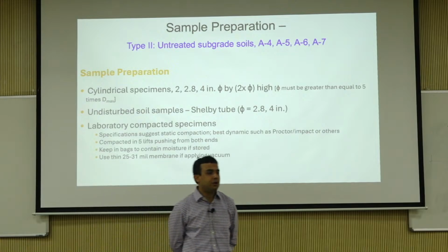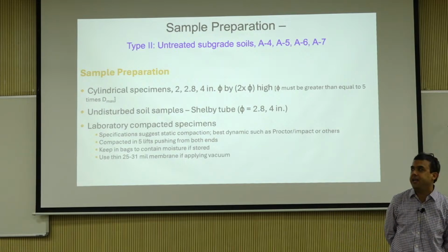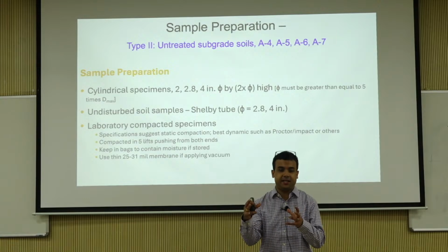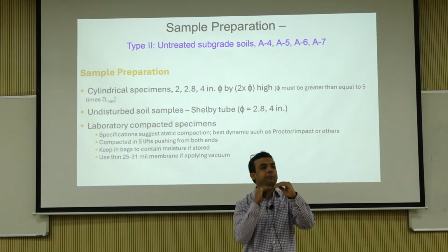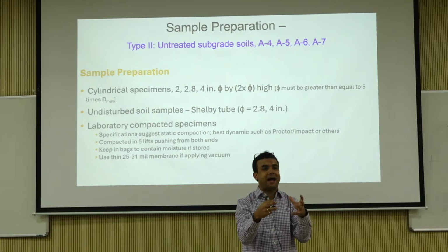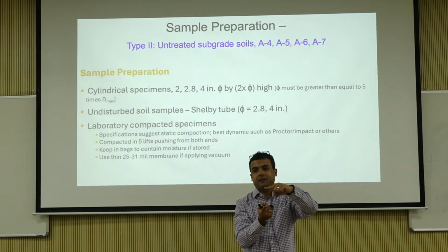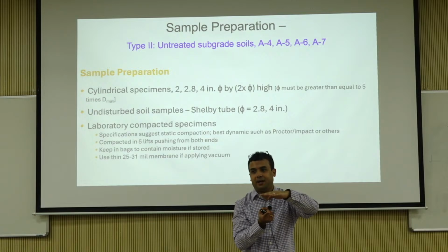Okay. So there are different ways. For example, the way I used to run it is I would calculate the target density. I know the volume of the material, and then I would say I'm going to compact in 5 layers. So I know the mass for every layer, and I know a target height for every layer. I do not stop compacting until I meet that.